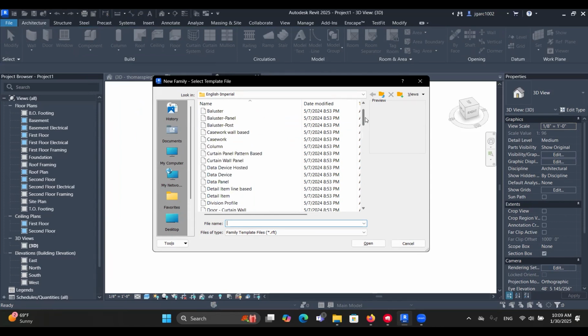So say you don't have the construction documents, but you do know what the parameters are, and you're designing furniture, a column, a curtain wall, anything here. You can actually create your own and then make it work in the project. It's going to read it as such, so when you do the schedules, it's going to place it in the schedules.